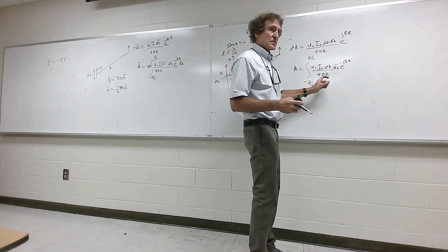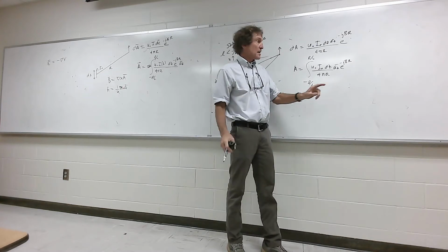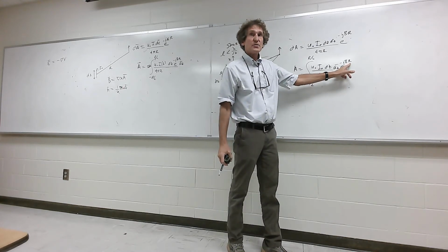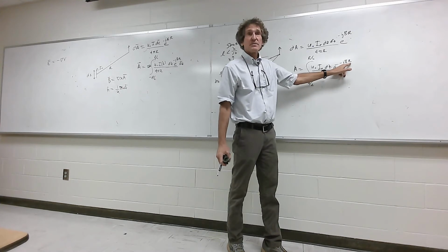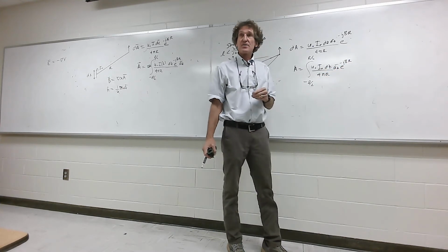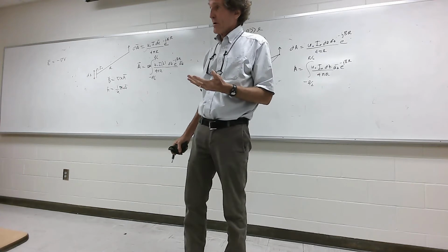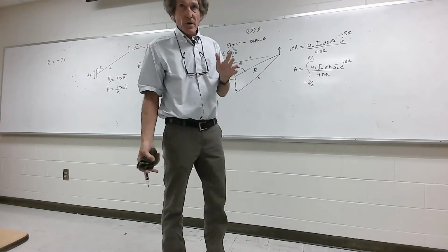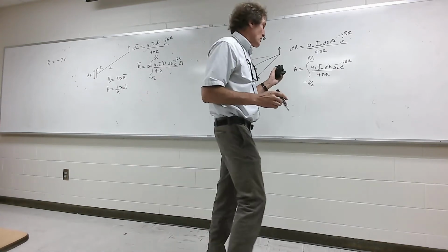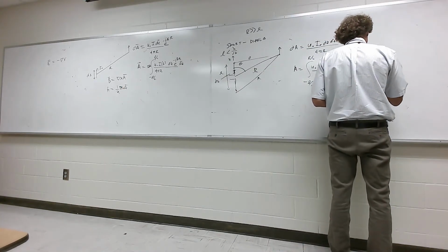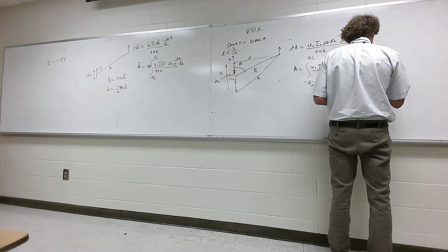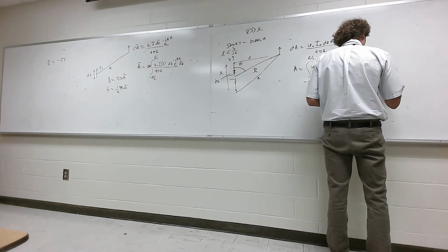What happens to this equation? The one place you can get stung here is this beta times r. Beta is 2 pi over lambda, times r. If r changed and it was near an order of a wavelength, then beta times r would make the phase on that term change quite a bit. But we're assuming a real short, electrically short dipole. What that means is this entire thing simply breaks down to this, after all that talking: I naught over 4 pi r.